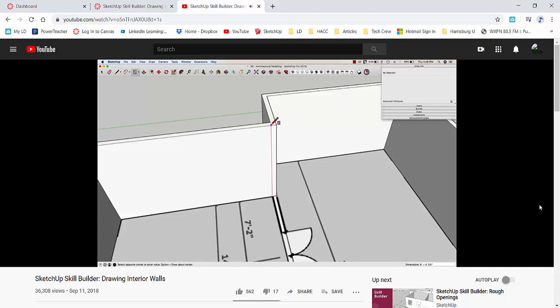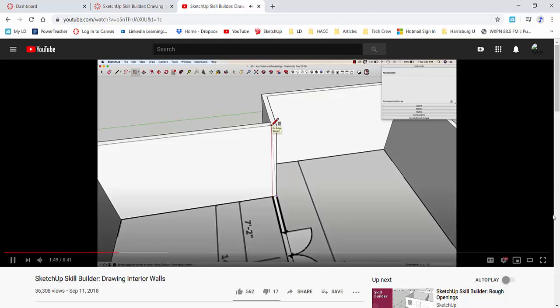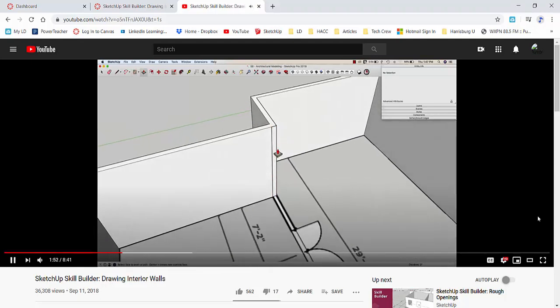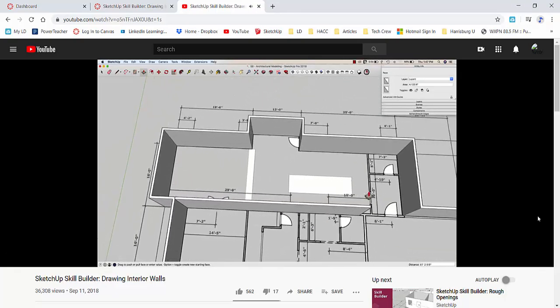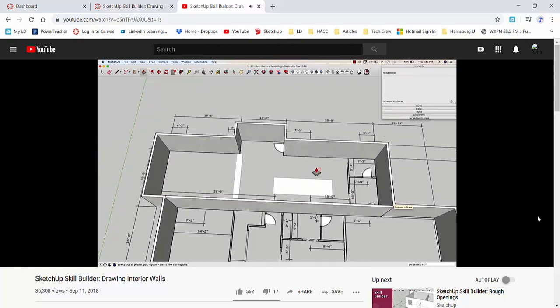I could come in here now and type the dimensions. I want this to be 9 foot by 5.5 inches, or I can hover over this back corner right here, pull it forward to the front, and look at my dimension there. 9 foot by 5.5. Perfect. And you can see the dimension down here in the bottom, 9 foot, 5.5 inches. Bottom right. Click right there. That gives me my first rectangle. And I go ahead and drag that all the way out to this opposite corner.